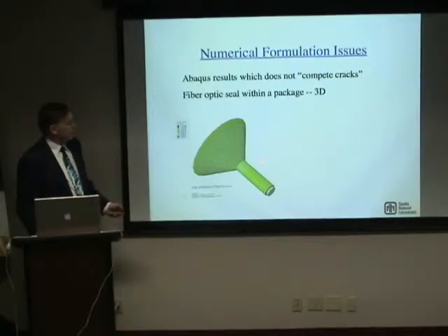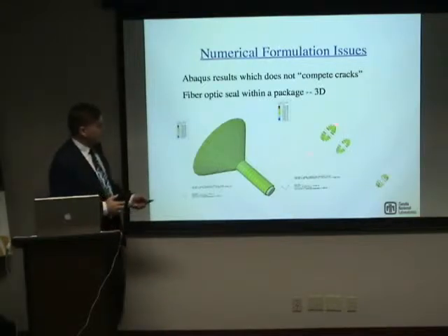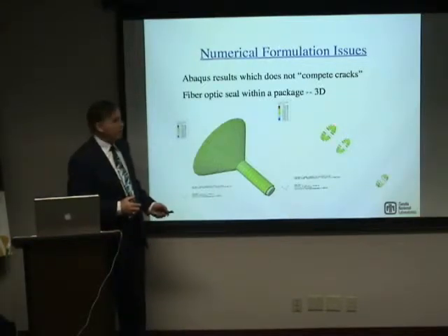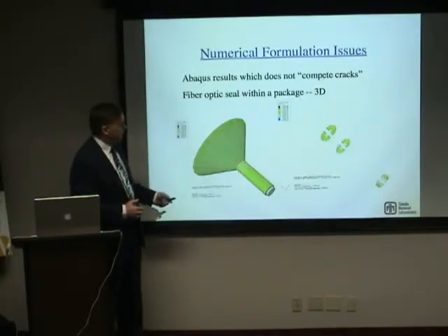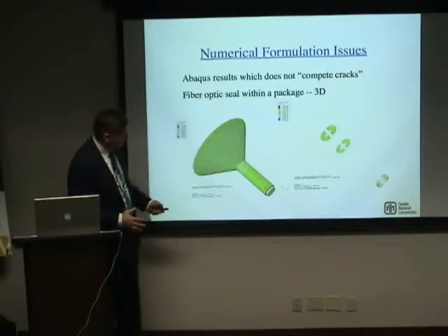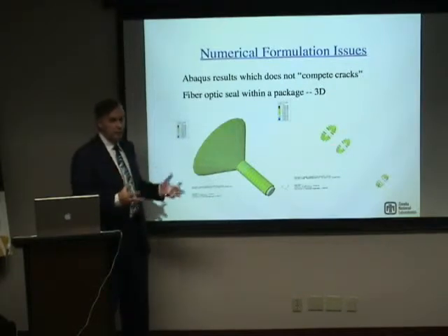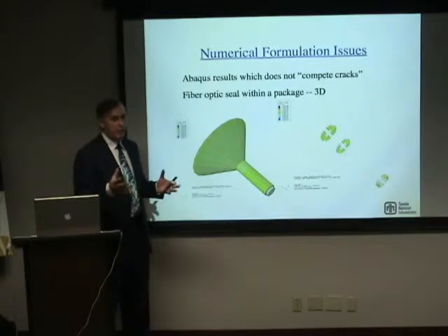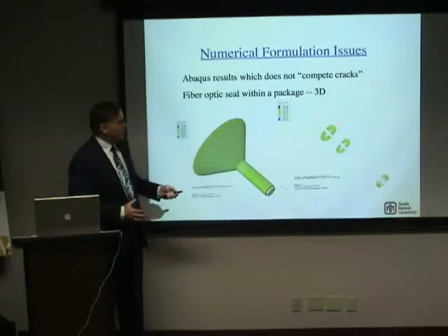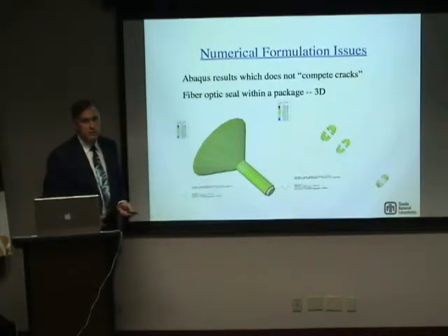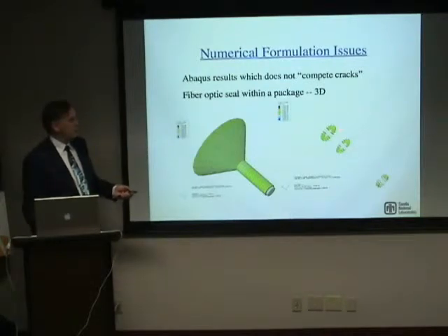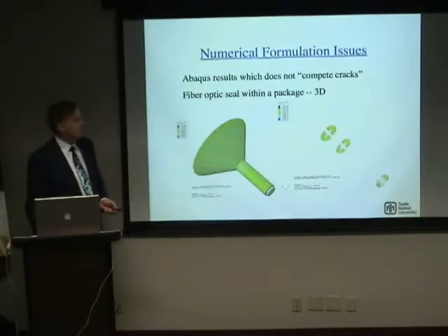Well, in this case, when we ran this initial 3D analysis, the first set of cracks we get in the context of Abaqus are these. They sort of look like turbine blades around an axle, right? So we not only have three regions where the crack started to initiate, but because of the definition of this problem having symmetry, and you can actually see the cracks on the surface right here of this real thin layer, because of the symmetry that we used in the modeling, the fact that we're treating everything as homogeneous, and Professor Gannon would be the first to say that's all a lie, and I agree, but because of these idealizations, we end up with this sort of radial deck of cards around each of these regions, because all of them are reaching, within the given time step, the criterion for initiating at the same time.